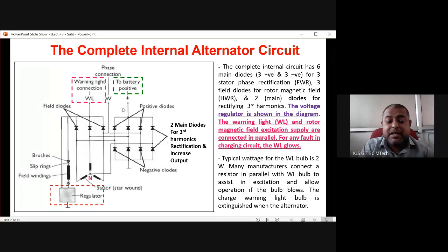These are the 8 bridge diodes which do not allow any kind of current from the battery towards the stator or the alternator. A very important thing to remember is that these bridge diodes stop any current flowing from the battery to the rectifier and the stator.